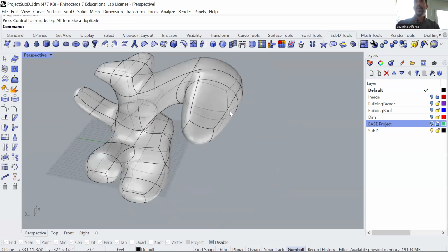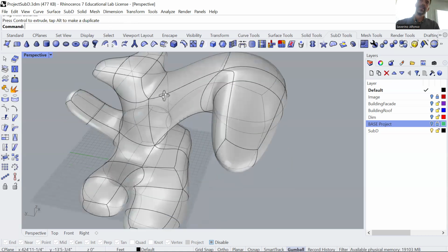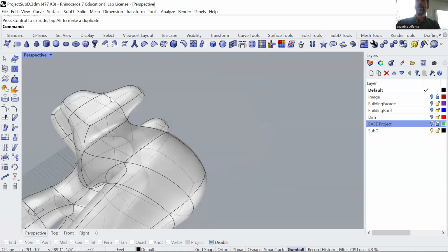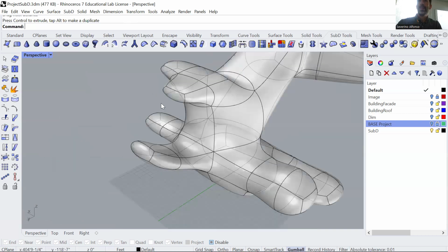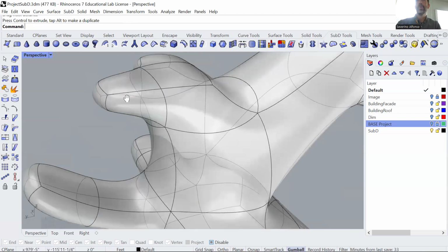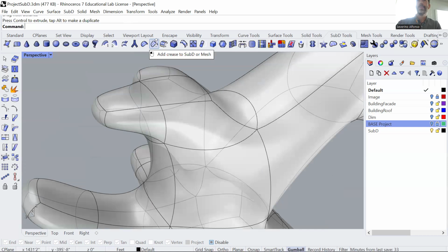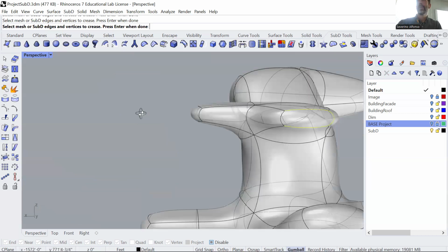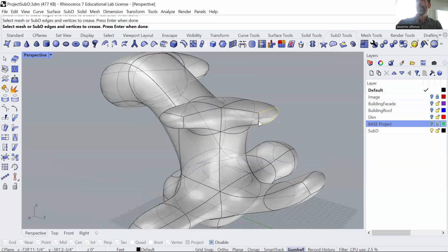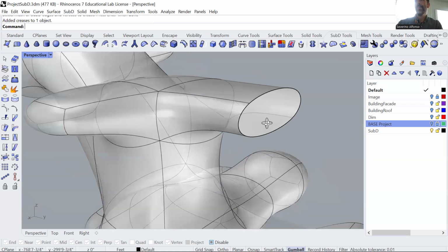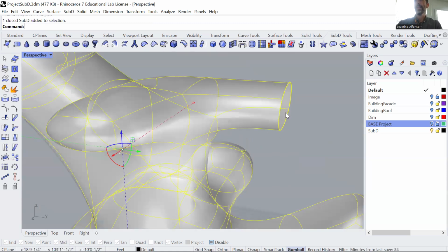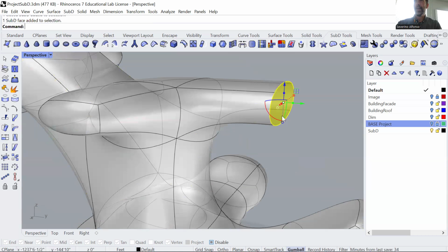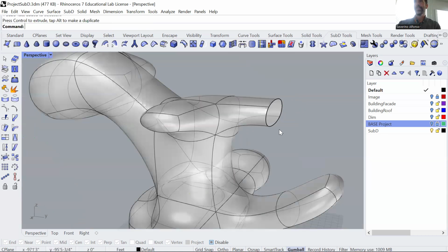There's another element that I think is important if you're going to take this to a serious level, which is the crease option. So if you select, for example, this is a smooth ending, but you could say crease. You can add the crease, select the number of faces. And if you press enter, it creates what feels like an opening, but it's actually a face that has a planar end to it, no?